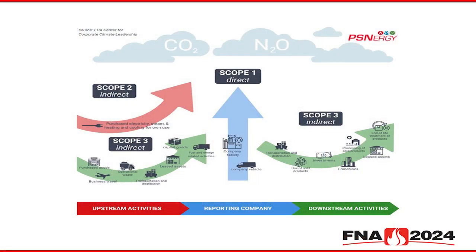Carl always says, if I have the data, now I can start to ask, what if I ran 12.5 to 1? I'm going to lose some efficiency, but I'm actually getting leaner, especially in open flame, and now I'm not forming an oxide on the part. So there are things you can do. But when you're just blindly doing things, you can get yourself in a lot of trouble. I know that people do that. We highly recommend they do not.